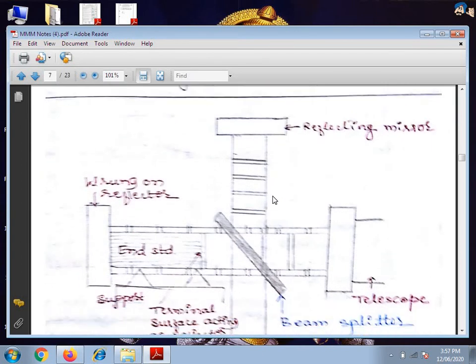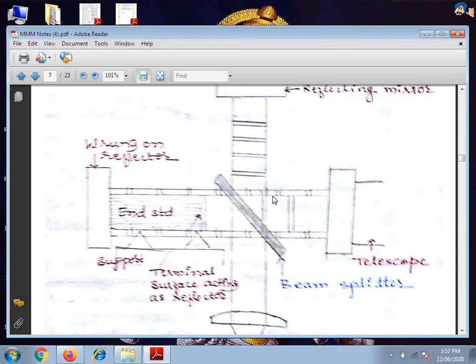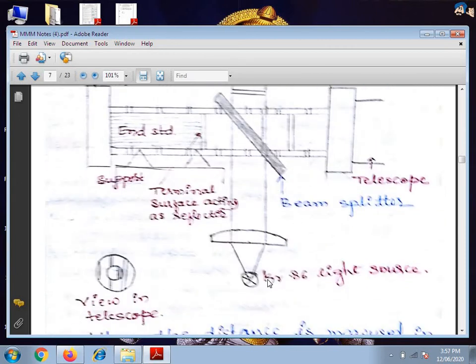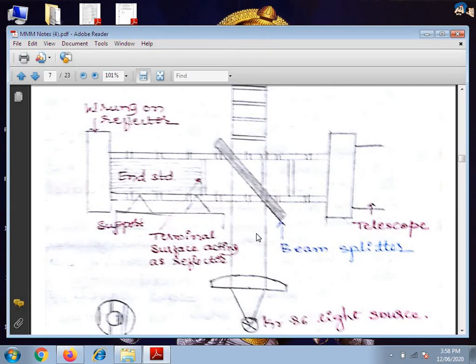The next one we are using is the wavelength standard. As you see, this is the source. The source means the light or waves produced. That light itself is monochromatic light. Usually for monochromatic light, totally 3 isotopes are considered: cadmium 114, krypton 86, mercury 198. Considering all the elements, they investigated, and finally krypton 86 is the best suitable to produce monochromatic light in order to get very good waves.